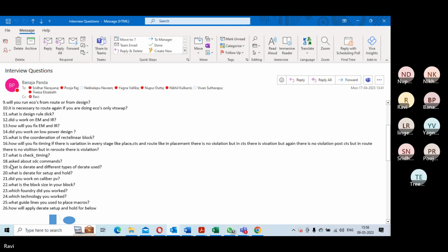But in this particular case we are talking about OCV, on-chip variation. What's the difference between OCV and AOCV? In OCV, each and every cell has the same derate value. Whatever derate we apply for pessimism is applied for every cell. What about AOCV? It is based on logic depth and distance between cells, and where the cell is positioned. So it is location based and logic depth based.